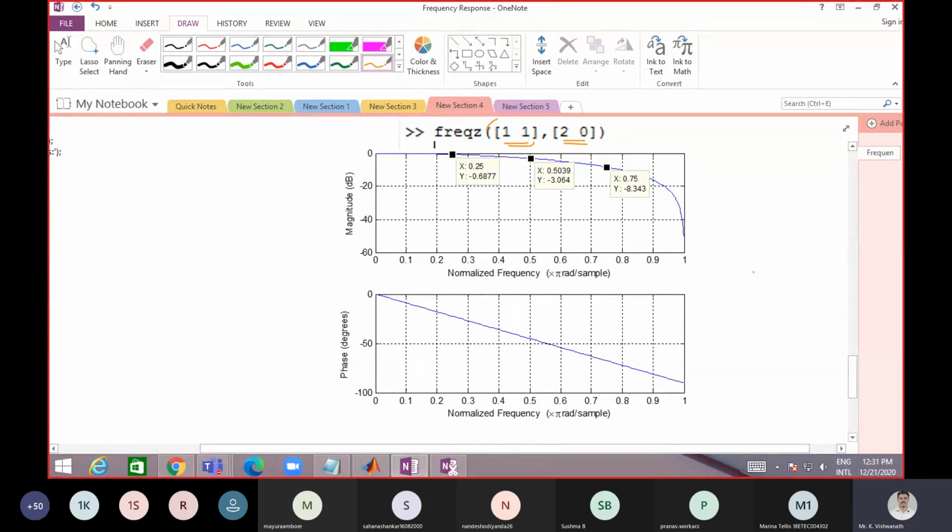The first term is called the magnitude response, and the second curve is the phase response with respect to the frequency. Whatever omega we have, with respect to omega we get a frequency. But omega, as I told, can go up to pi maximum, and here we are representing pi as 1, so it is normalized. We can say multiples of pi radians per sample.